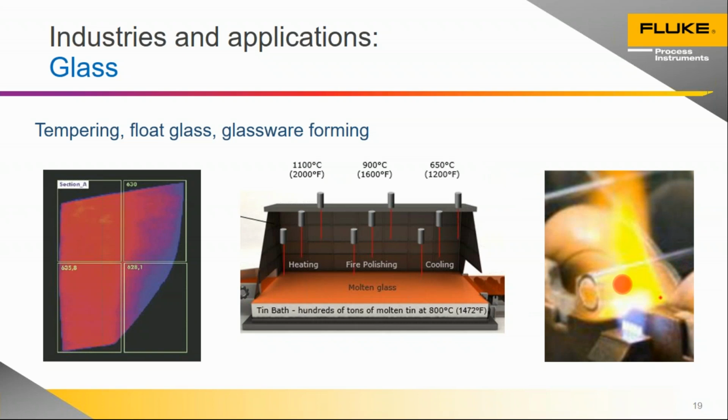Generally, this starts off as a long kind of tube stock of glassware cut into small vials and then formed into what it needs to be. And in some cases, you have purification processes in the end, which are also heat dependent. And we have some thermal imagers being used in those applications to ensure that they reach a sufficient temperature to achieve purity and such.